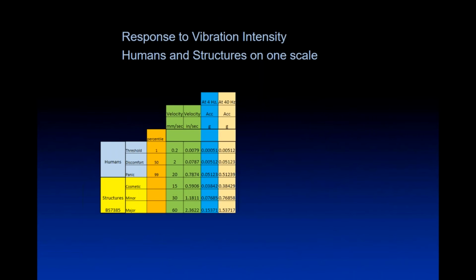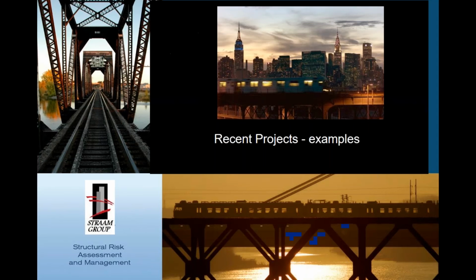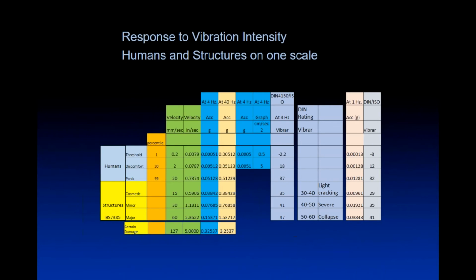This is, by the way, at the same location, measuring by conventional means, and you can see this is using a device which operates on velocity. It gets the frequency wrong because of noise in the system. So it says that it's a much higher frequency, and that shifts all of these points of vibration intensity across to the right of the chart. We had some instances where it was higher up here, again at the right of the chart, but if the frequency is taken back to what it really is, it can cross those thresholds. So the form of measurement is extremely important.